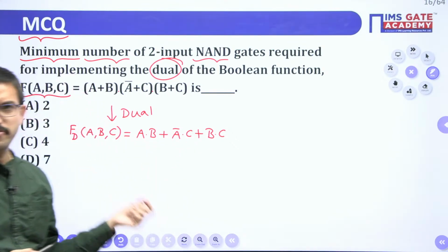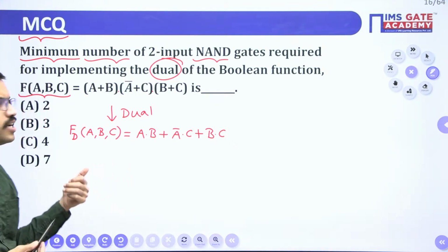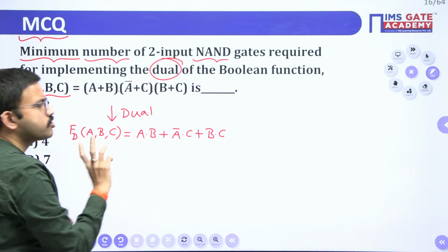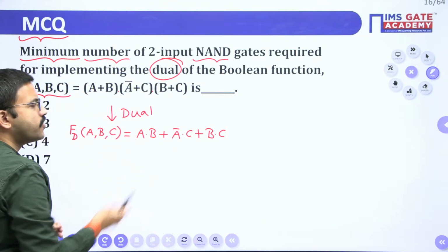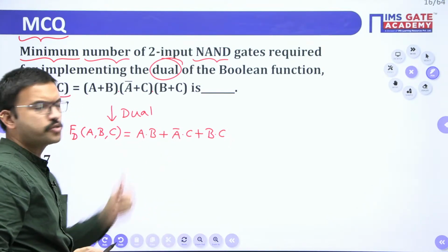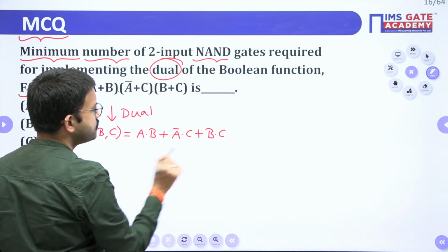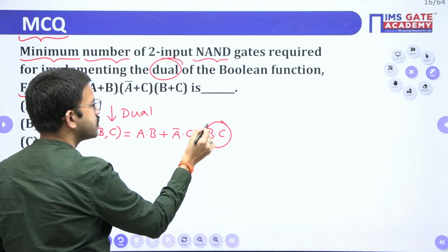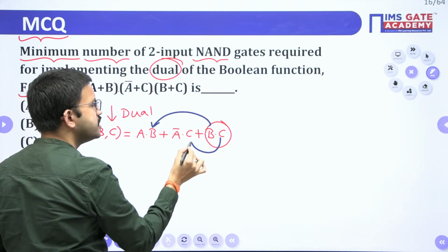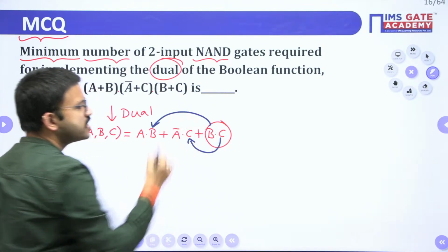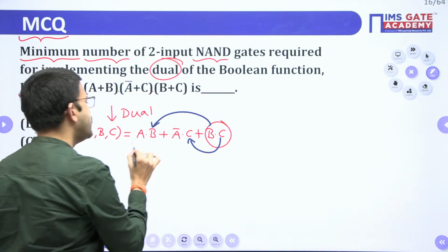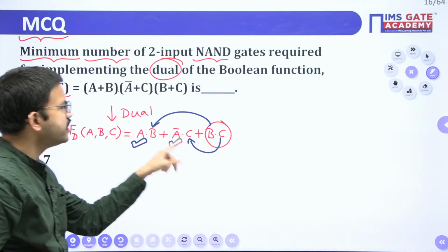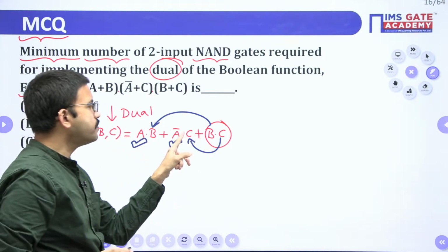If you want to do the simplification, in the last class we discussed the consensus law. With the help of consensus law, you can cross check whether those conditions are satisfied or not. If satisfied, then we can bring these three terms to two terms, right? If you observe, I am considering the last term, BC. B is present here and C is present here. In this particular term, the missing variable is A. That is present here in normal form and in complement form here. A can be present here, A bar can be present here, and B can be present here, C can be present here.